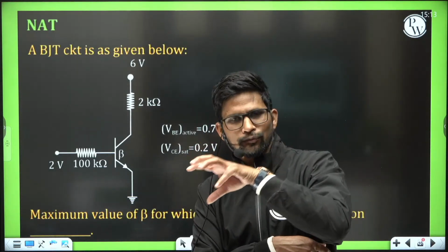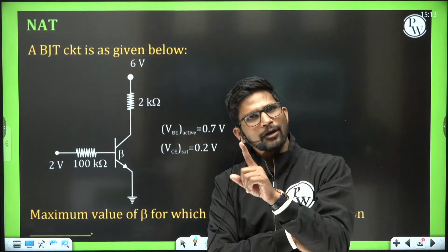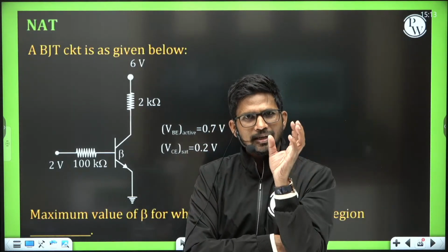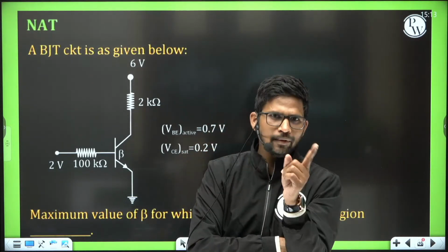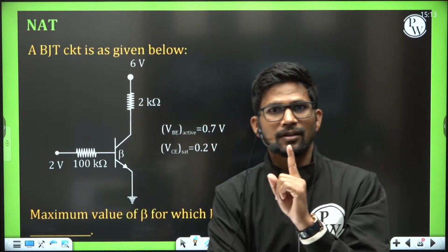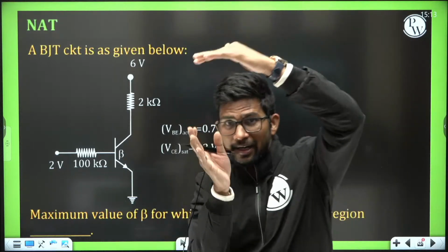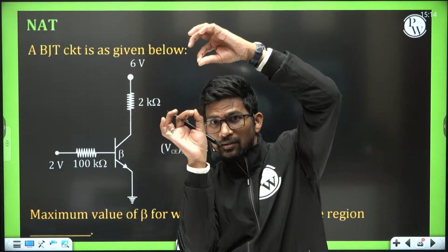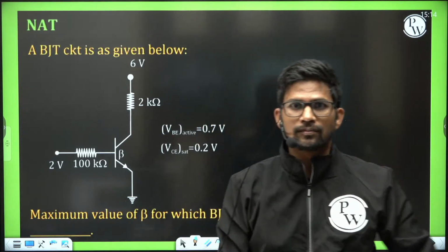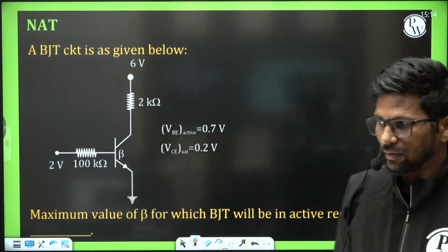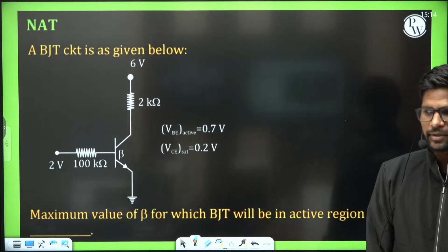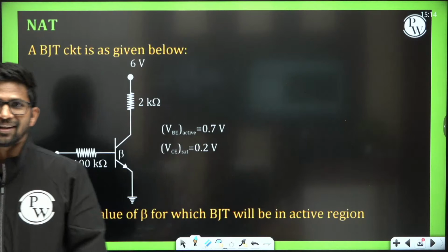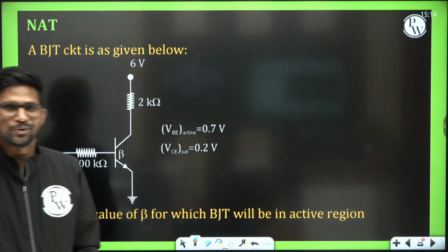Then when you apply KCL, only I naught will be unknown and the others will be known, and then by incoming current equal to outgoing current, you will find the answer of I naught. So you need to find out the other branches' currents apart from I naught at the output node. Always remember this in mind. Don't fail KVL and KCL in op-amp questions.